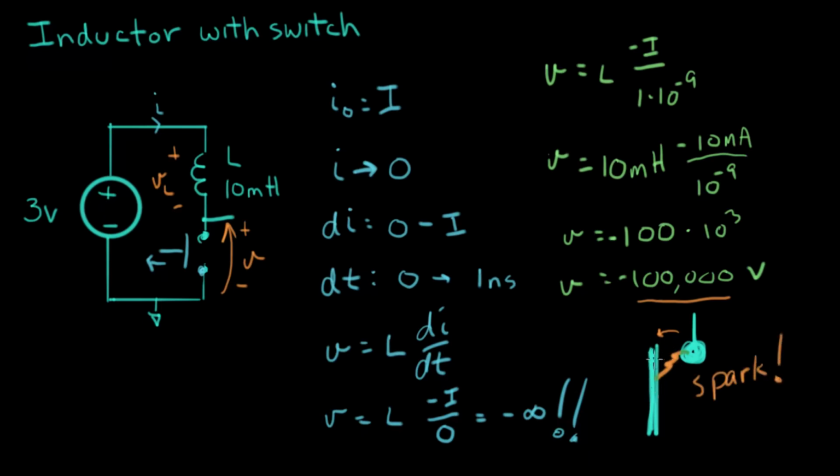This really happens in real life. When you open a switch, there can be a little spark that goes between, and that gives this equation, this dI/dt, enough time to release that energy, and that current from the inductor continues to flow and go over into the switch. That current will flow, and it does it by breaking down air molecules.